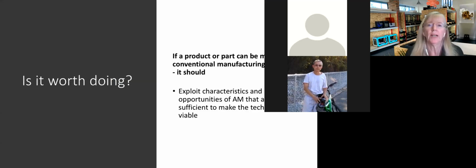So the first question really is it worth doing? So essentially, my opinion is that if a product or part can be made using conventional manufacturing technology at this time, it should. If it can be made using conventional manufacturing technology. In other words, the only justification to me for using additive manufacturing is that it's exploiting the characteristics in additive manufacturing that add value sufficient to make the technology viable. It might change in the future.